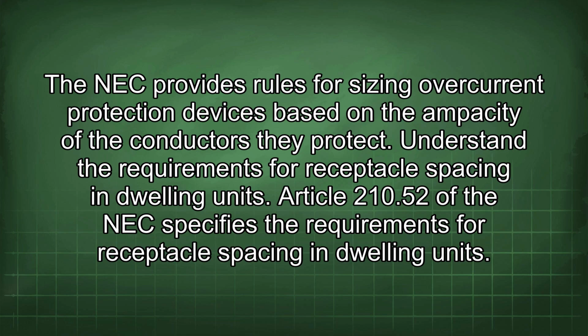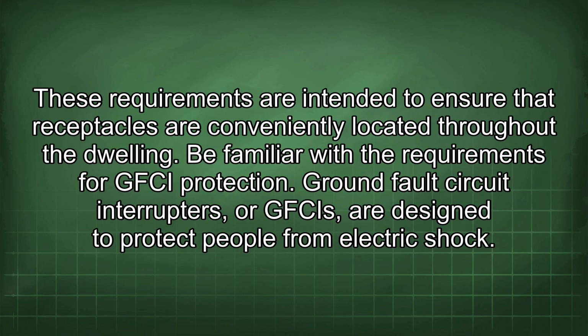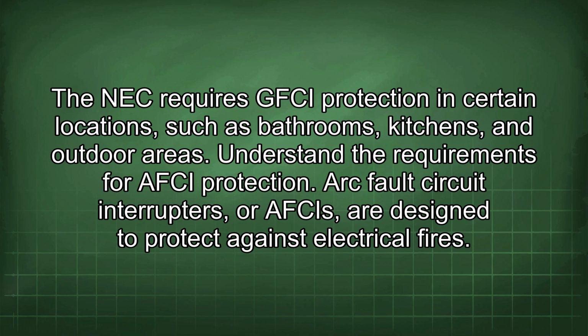Understand the requirements for receptacle spacing in dwelling units. Article 210.52 of the NEC specifies the requirements for receptacle spacing in dwelling units. These requirements are intended to ensure that receptacles are conveniently located throughout the dwelling. Be familiar with the requirements for GFCI protection. Ground fault circuit interrupters, or GFCIs, are designed to protect people from electric shock. The NEC requires GFCI protection in certain locations, such as bathrooms, kitchens, and outdoor areas.